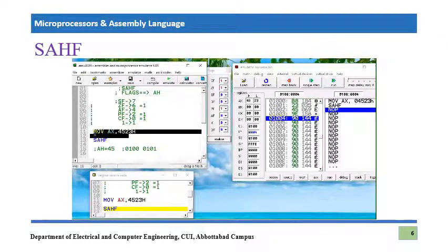Let's take, this time I'm just gonna use 8-bit. 59 hex. Okay, so I'm going to convert it directly into binary: 0101 1001. So according to that, bit carry flag is high, and third number bit is not connected with any of the flags, so it is not concerned. Fourth number bit is auxiliary carry, it is high, and sixth number bit is ZF flag. So these flags will be equal to 1, and remaining flags will be simply 0.